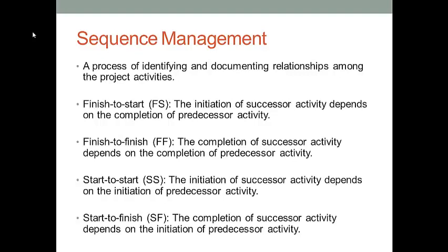Third, we have the start to start sequence. This sequence shows that the second activity will not start until the first activity starts. Lastly, we have the start to finish sequence. This sequence shows that the second activity will not finish until we start the first activity.